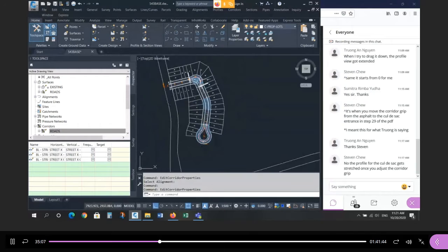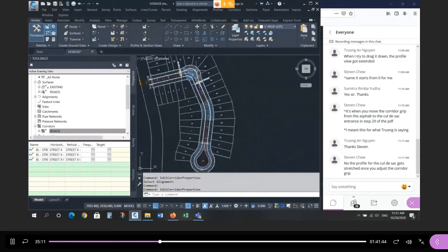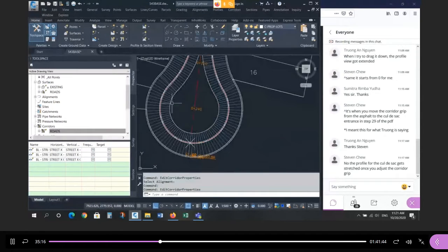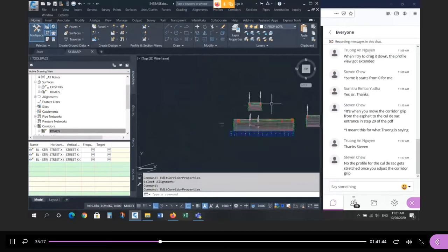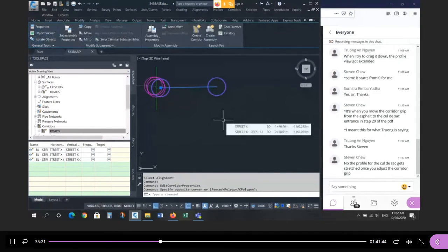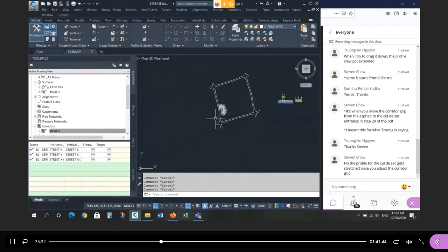The hole in the middle is the same issue we had here. Remember, there was that kind of break in the pavement. What we need to do is exactly what we did here. I guess just the geometry is different. We want to take this piece, the pavement. Let's go back to the cross section. I want to take the pavement piece and use that targeting function to make it longer. I want to extend these all to the center line horizontally, and vertically I want it to match the elevation of the center line. Okay, so that's a targeting issue.